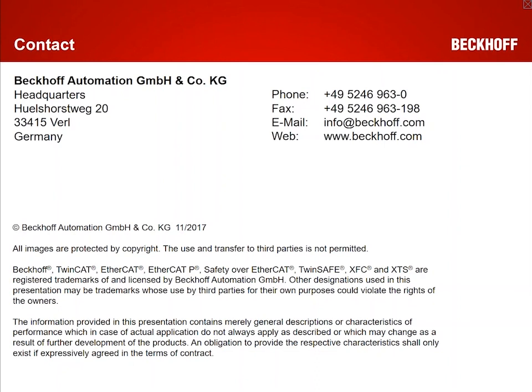If this is the case and you need this signal for debugging or monitoring purposes in the TwinCAT block diagram, you can go to Simulink and you only need to set a test point on this specific signal. Providing a test point is something provided by MathWorks, so it's not something specific to Beckhoff. Then the optimization will be such that the signal is still visible in the block diagram.